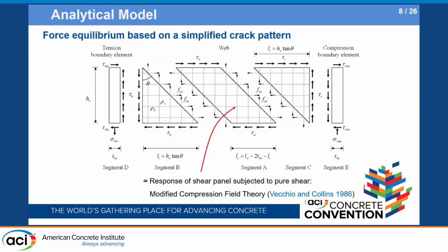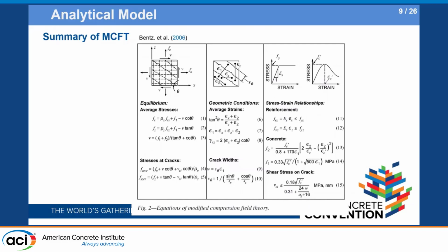And we use modified compression field theory, which is very useful for this kind of in-plane shear problem. We applied this modified compression field theory to calculate the shear stress and rebar stress of the web, and we successively calculate the force demands applied to both boundary elements. If you're not familiar with MCFT, this paper is a good summary.